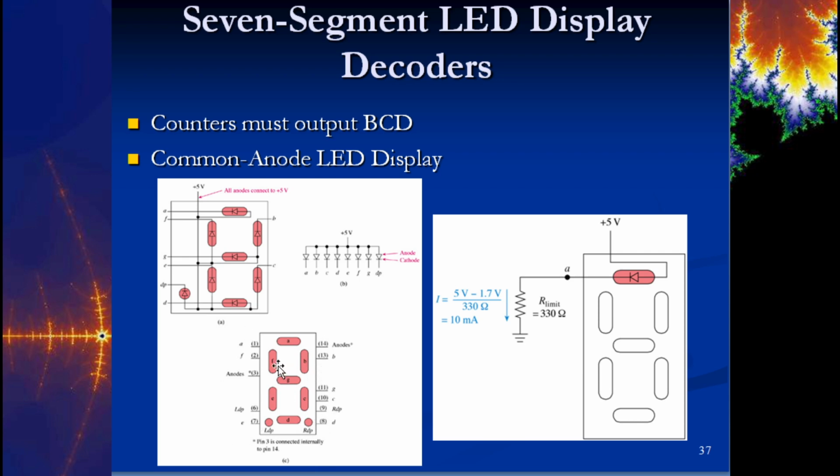There are ones where, if you're following my cursor here, you see these segments A, B, C, D, E, F, and then the middle is G. That's the 7-segment standard. If you have more of them, you could have an 8-segment, a 9-segment, a 10-segment. Sometimes through the middle here, you'll see 2 slants so that if you wanted the letter K, you could have this segment on and this segment on, and then this diagonal and this diagonal.